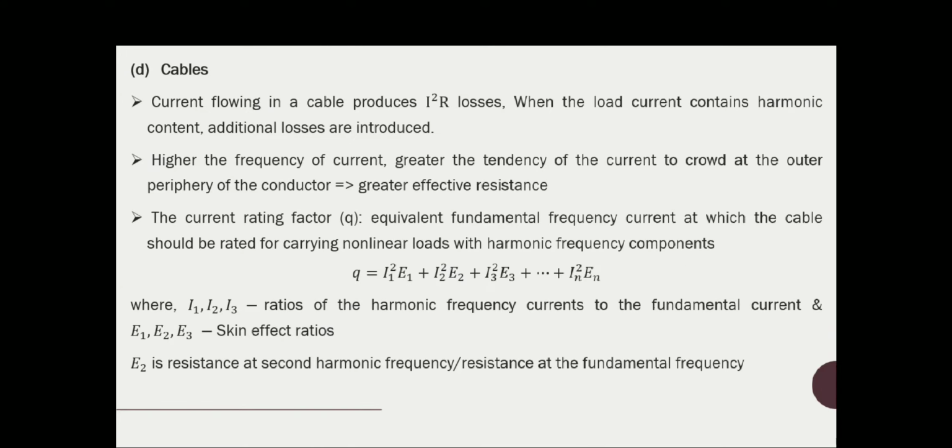Then what are the effects of harmonics in cables? You can see that current flowing in a cable produces I squared R losses, and when the load current contains harmonic content, additional losses are introduced.